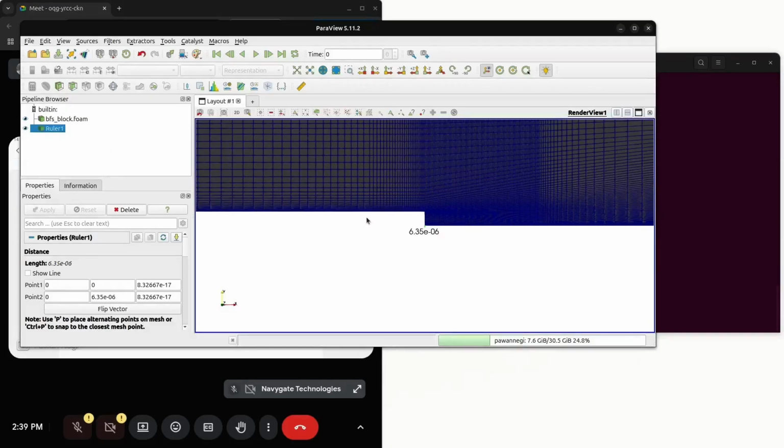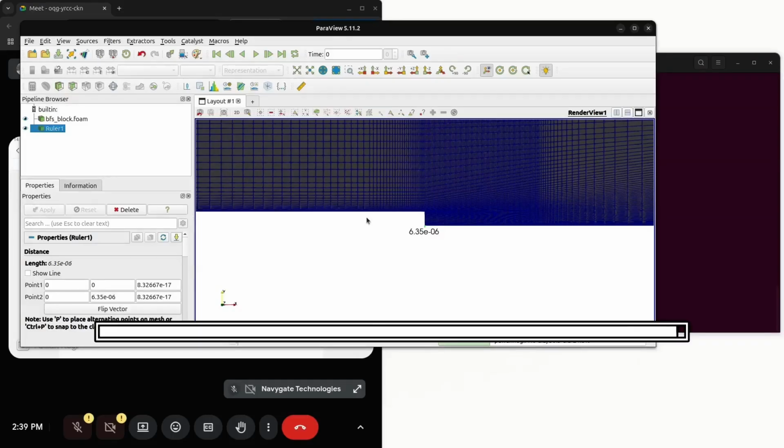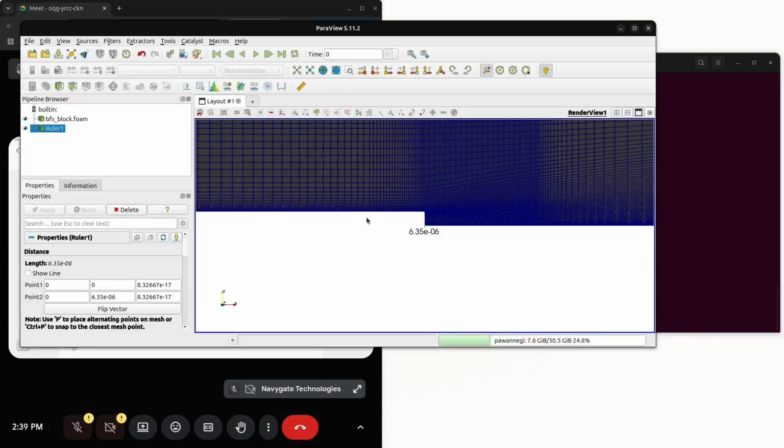Learning how to create this kind of mesh requires practice. This will be done in some other course. We'll use this particular mesh for our analysis. We'll see how the results are affected by different turbulence models on this particular mesh. We have also seen that triangulations create a lot of mesh, and the process is mostly automatic, and there are alternatives to that which are already present in OpenFOAM. So in the next lecture, we'll use the Launder-Reece-Rodi model to simulate the flow over the backward facing step. Thank you.